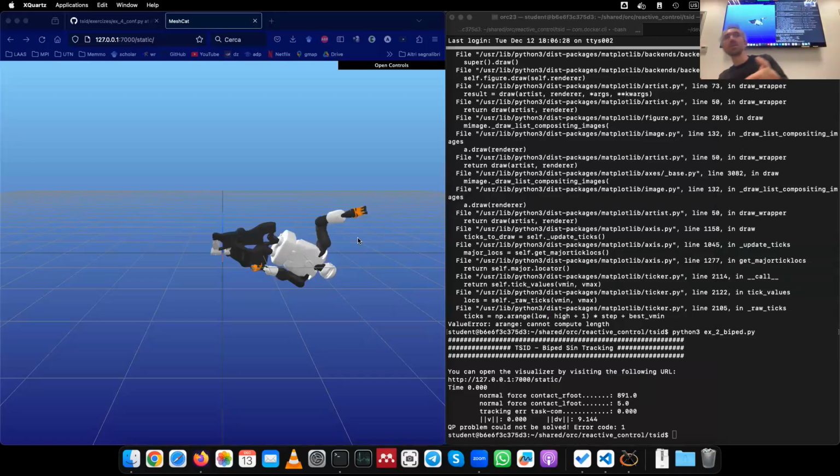You cannot move your center of mass basically beyond your foot to the sides and then come back without moving your feet. You just fall down because of gravity. So this should highlight the importance of having a reference center of mass trajectory which is compatible with the limitations of the robot, which is going to be the main subject of the next hours together.